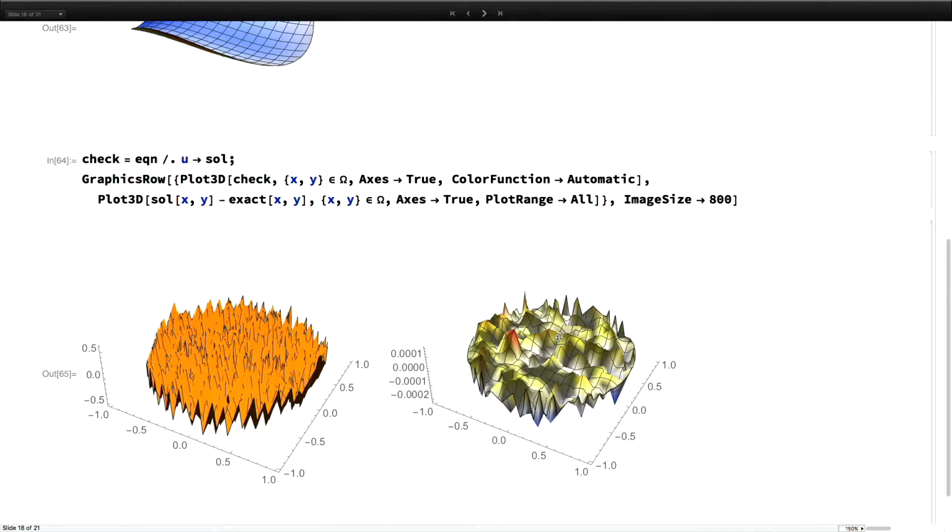But on the left-hand side, you have a residual. And the residual is not coming out correctly because when you're doing finite element analysis, the highest order derivative goes down by 1. So that highest order derivative information ends up having a really bad approximation in the interpolating function. So if you do this kind of residual checking, make sure to keep these things in mind. And I think that's pretty much what I wanted to cover.